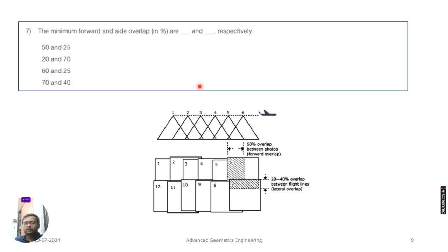When you capture these photographs from the sky, it is like parts of a jigsaw puzzle where you do not know how they will fit with each other. You have to stitch those images together to make a combined mosaic, and from that you can make 3D images also. So for that, this overlap is necessary.